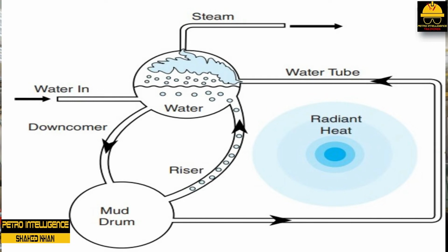Each time the water passes through the tubes, it picks up more heat energy. When the pressure increases to slightly above the system pressure, steam will flow through the non-return valve into the system. Boiler load is a term used to describe the plant's demand for steam.